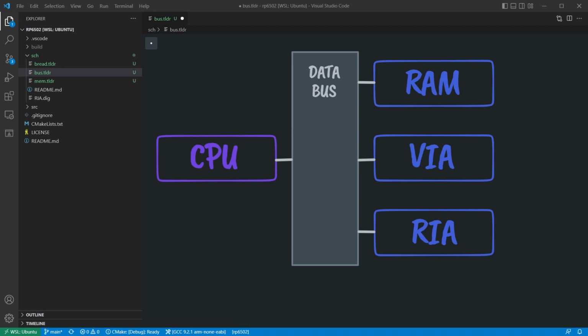To understand that, we need to look closer at the data bus. If the 6502 is writing, it'll be driving the data bus with CMOS logic. If it's reading, the data bus will be in a high impedance state, so something else can drive the bus. Only one chip at a time can drive the bus. Knowing if you should drive the bus requires looking at both a chip select and the write enable signal. If we build a truth table for the PyPico RIA, it looks like this. These three states affect how I need to write the next PIO program. While chip select isn't technically needed yet, I didn't want to rewrite the PIO program later to add it.